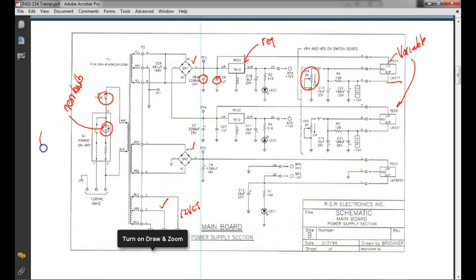So it looks like this. It comes in like this, and then we got two plates because they're not actually touching. But what you got right up here, I can't draw, is a little dot. That's the symbol for a neon bulb. They work off AC. They have a high voltage rating on them. So I think that the ones we have are rated at 120 volts.